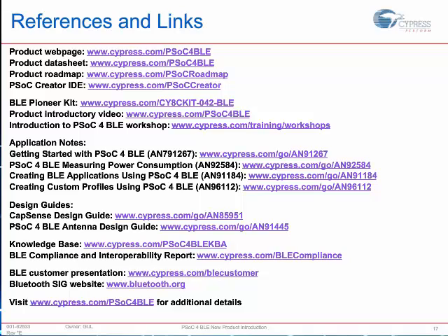So for the first question, is the EZ-BLE available all set up to do BLE to UART right out of the box? So the EZ-BLE is available in two ways. One way where the BLE stack is exposed to you, the user, and you can implement your own profiles and your own topologies on it. And then it's available in a second form factor where it is simply a BLE to UART module where you don't have to worry about developing with it in PSoC Creator. You just communicate to it over UART and configure the entire BLE stack and profiles over UART. So both options are available, yes.